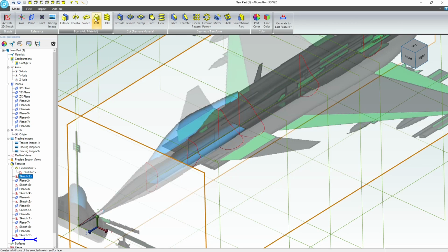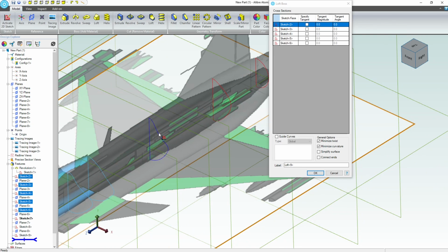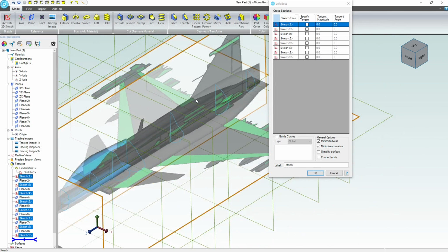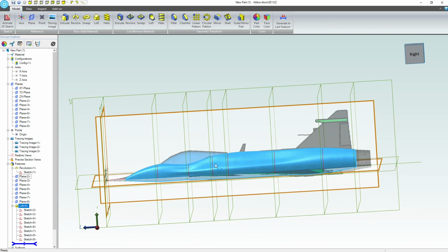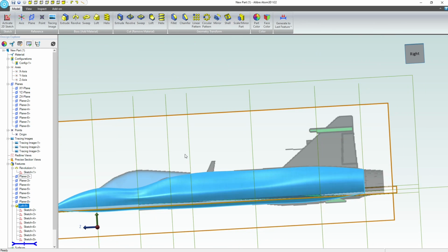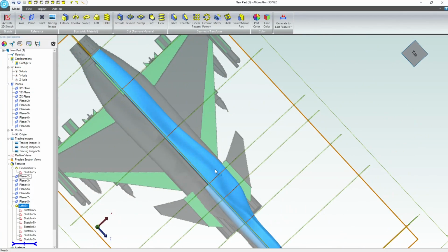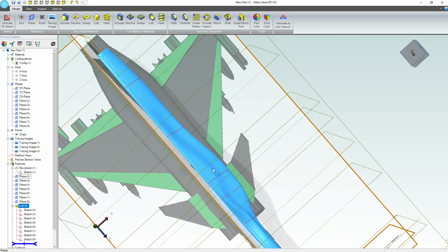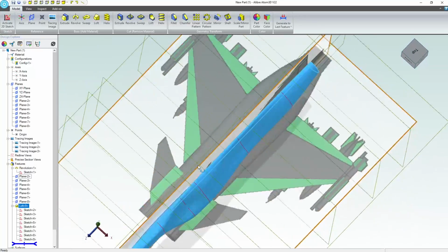Starting with sketch 2, we're going to create a loft to sketch. And I can choose from the graphics display. I think it's easier to visually see it. All of my cross sections. And let's see how we are without any additional. That fits really well. And this reduction here in diameter, as it comes down and you get sort of a taper downward, that's for efficiency. You get less drag with that taper, substantially so actually. And yeah, we are looking a lot more realistic to how the Gripen actually looks than my first run. So I'm very happy with that.